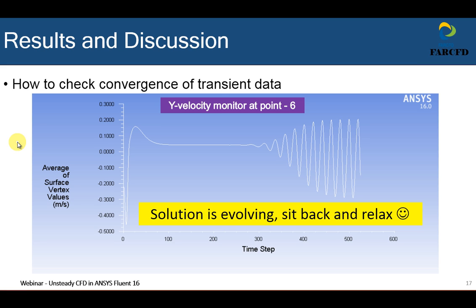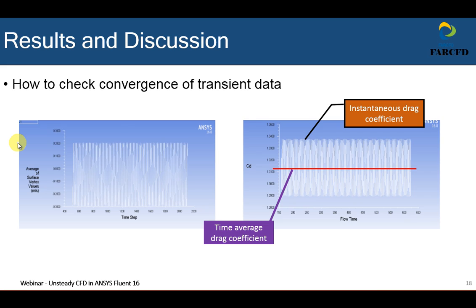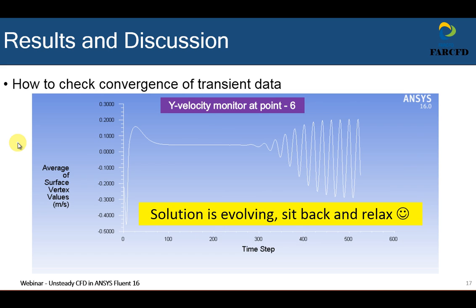Sometimes, CFD users try to solve unsteady problems using the steady-state approach without knowing it. However, it is very easy to find out that your current approach is wrong by looking at the residuals and other monitors when they begin to show a cyclic increase and decrease in magnitude. Now it is time to switch to unsteady CFD.